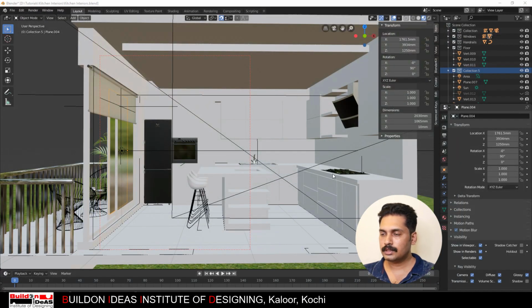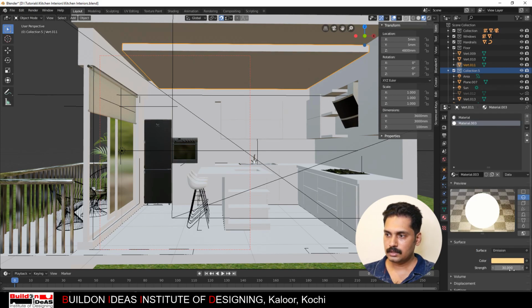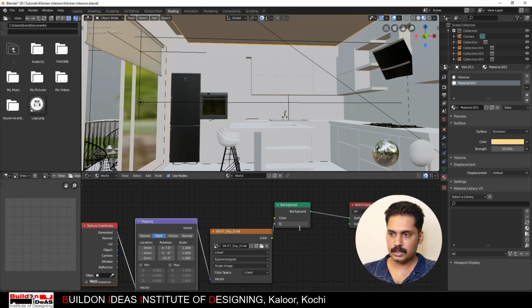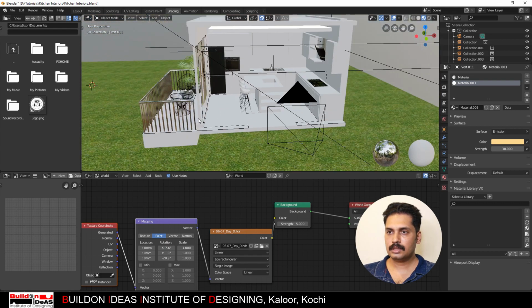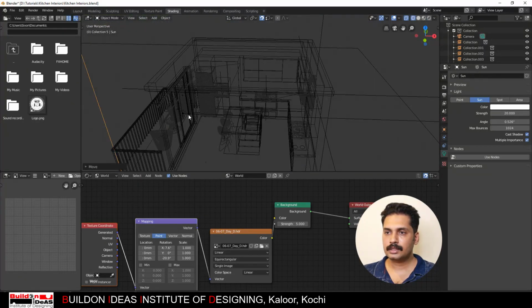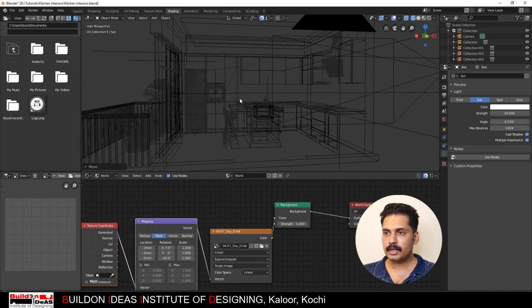So we'll just reduce the value of this light slightly by going to the materials and then make it as say 30, and then I think the environment is also having some, so I'll just make it as 5 and I'll just save it. Now what I'll do is like I'll just slightly tilt this light so that you'll have nice shadows. What you can get by changing the light is that you get the shadows slightly slanting, so that looks much better in the view.